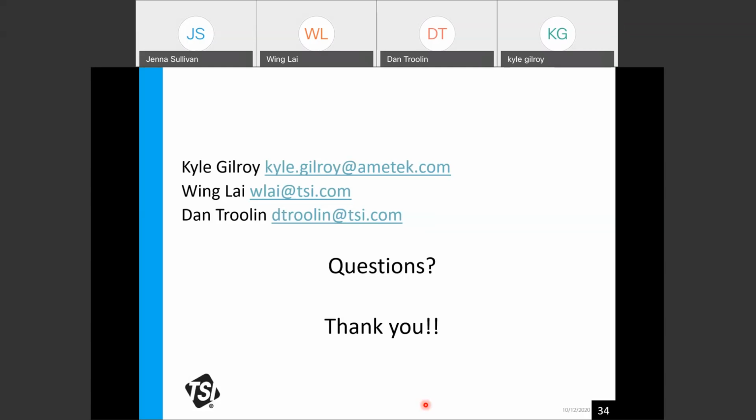Yeah, Dan. So again, depending on the time between the two laser pulses, and like Kyle was mentioning, we can actually capture two images with about 200 something nanoseconds between the two frames. So effectively, we can make measurements up to maybe even 1,000 meters per second, of course, depending on the field of view of the image capture.